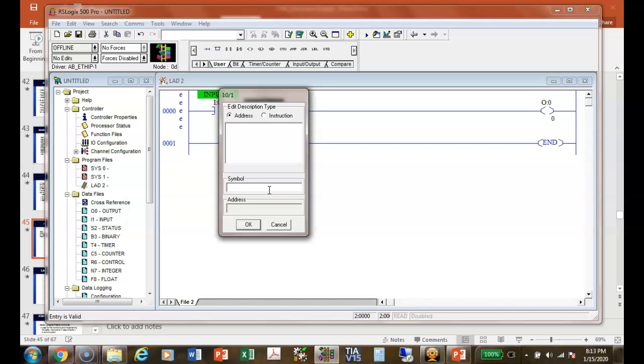What do I hook up to that? Well, any input. It could be a push button. It could be a sensor. It could be anything. All it says is, okay, if that input is true, then that simulated contact would close. These are not contacts. These are all simulated, right? Does that make sense?